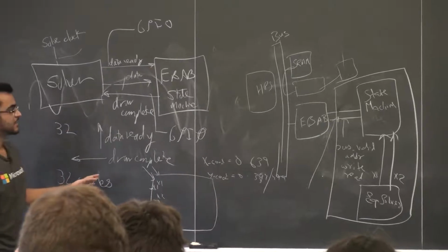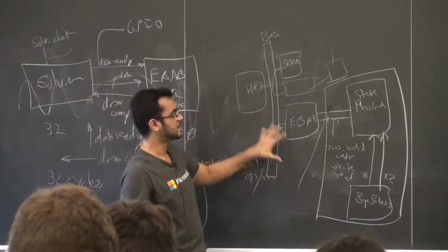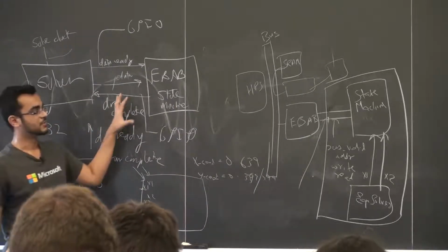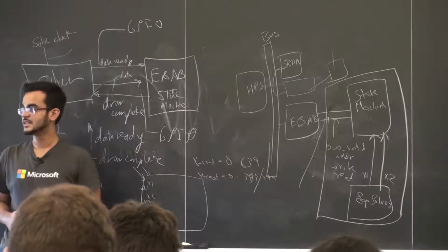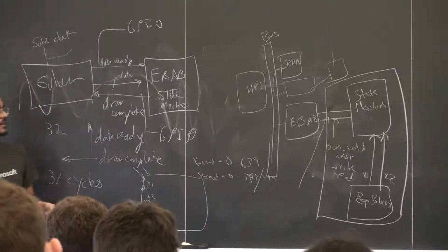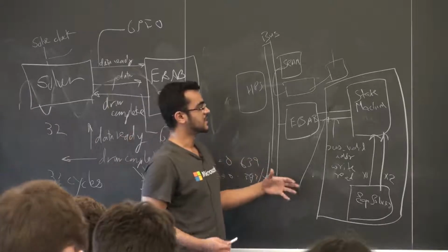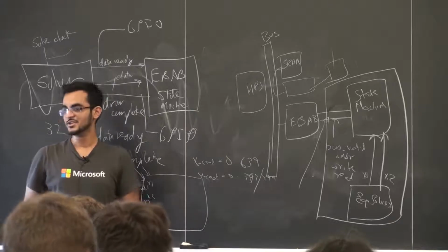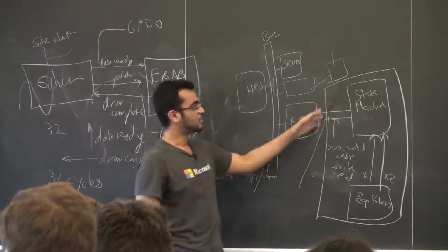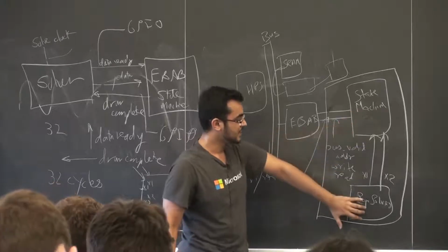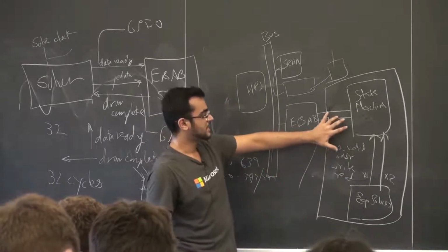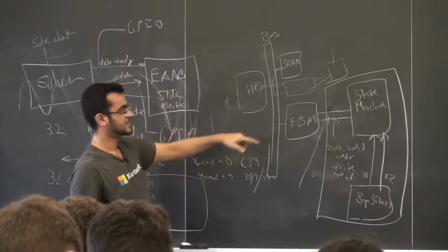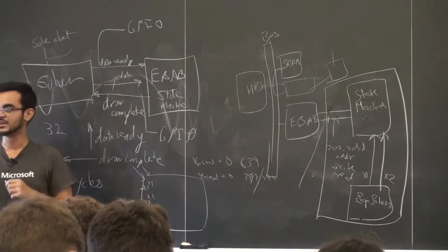Once we are sure that everything is running fine, then I would integrate the entire system and watch things on the monitor. I think that is a good way, instead of just building systems where it takes 10 minutes and then you don't see anything on VGA and you are stuck with your debug. One way to go about this is to take your state machine and your equation solver, do some simulation, monitor what transactions are going on, and based on that figure out what you are doing wrong.